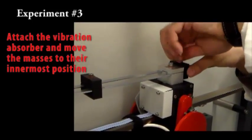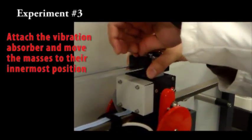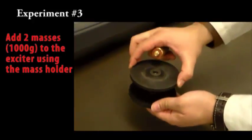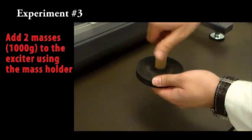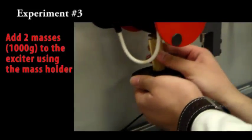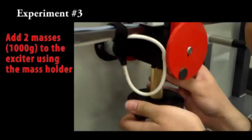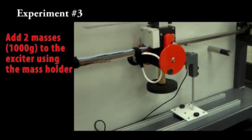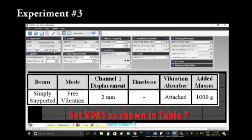Set the masses of the vibration absorber to their innermost positions so they form a basic load, but cannot vibrate. Each mass is 14 millimeters thick, so their mass center is at 7 millimeters. Add 2 masses to the exciter using the mass holder. The total added masses with the holder is equal to 1,000 grams. Set VDAS according to Table 7.